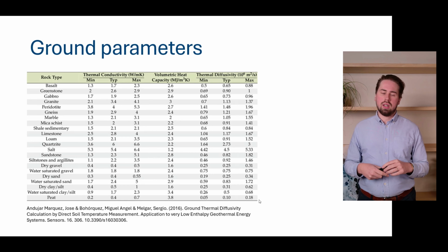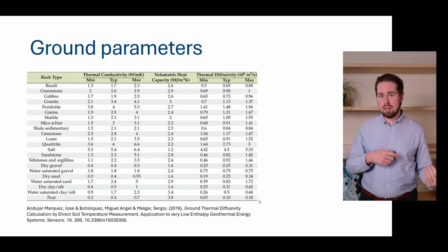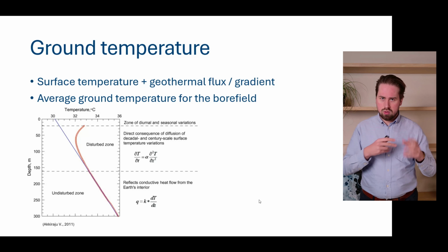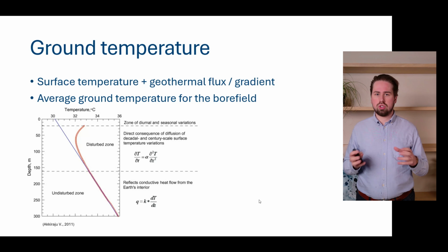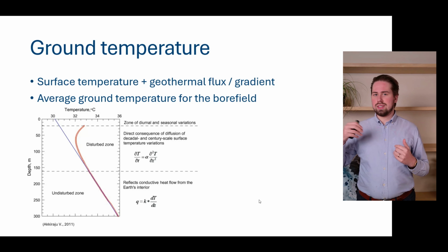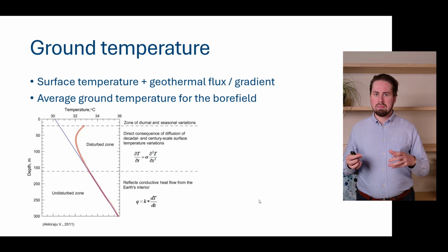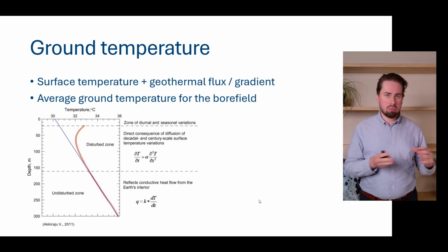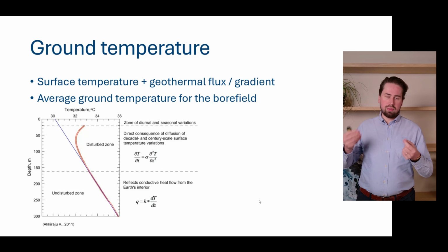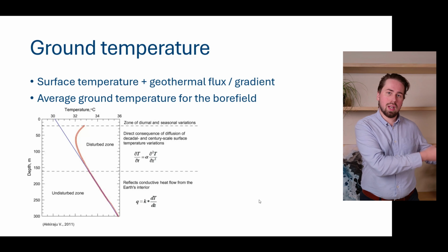That's also an important aspect because it determines quite a lot your volumetric heat capacity and your conductivity. Another parameter that is important besides thermal properties of the ground is the ground temperature. Because if you recall a temperature profile, it starts somewhere. And depending on your location or your borehole depth, your initial temperature can be 10 degrees Celsius or 13 degrees Celsius. And that, of course, determines where your temperature profile starts and hence also where it will end.